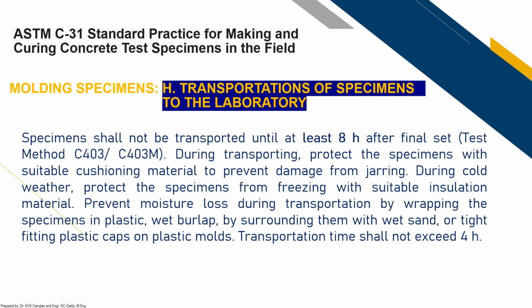Okay. So, one distinction again of ASTM C31 against ASTM C192 is the provision on transportation of specimens to the laboratory, since we are dealing with provisions under field conditions. Okay, so specimens shall not be transported until at least 8 hours after final set. Okay, test method C403 or C403M.